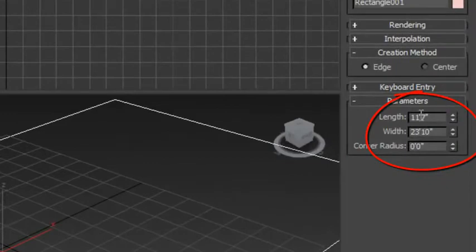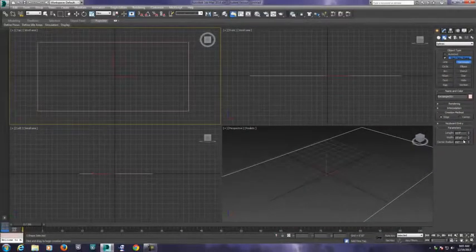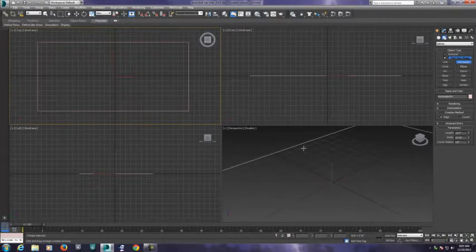You're going to see that it's actually measured in feet and inches, and that's important because as we build the scale model, we want the furniture to look right, but then later down the road we're going to use photometric lighting, which relies on real scale models in order to work right. So ultimately, not following this first step could be critical to the professionalism of your entire model.